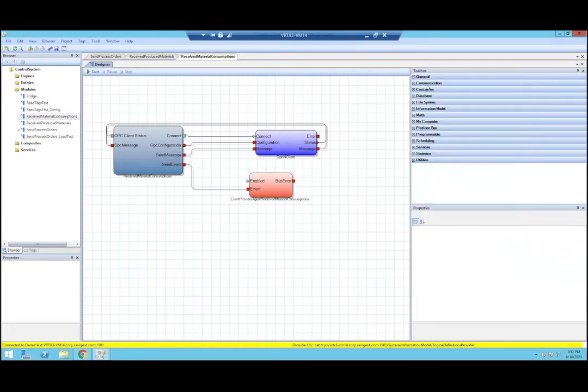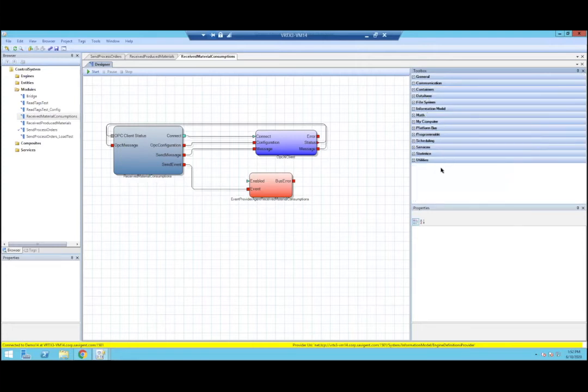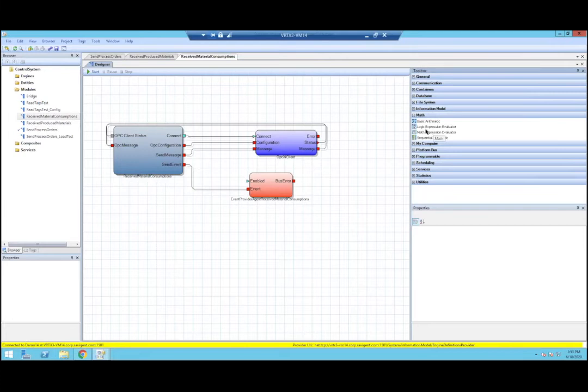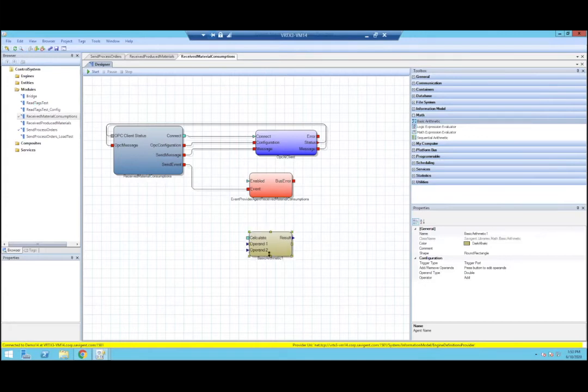If I take a look in our toolbox, you'll see these are a lot of the categories that Mark was talking about earlier. I don't have all the agents loaded on here at the moment, but there's OPC agents, Kafka, Serial, TCP, database agents. When I'm ready to use one of these agents, maybe I'm just going to go to my math agents that I have loaded on, and I can drag and drop a basic arithmetic agent onto the screen, right? And I can basically hook up the operations that I want this arithmetic agent to work on, and then I'll end up getting a result. And I would configure that with the properties, again, that are here.